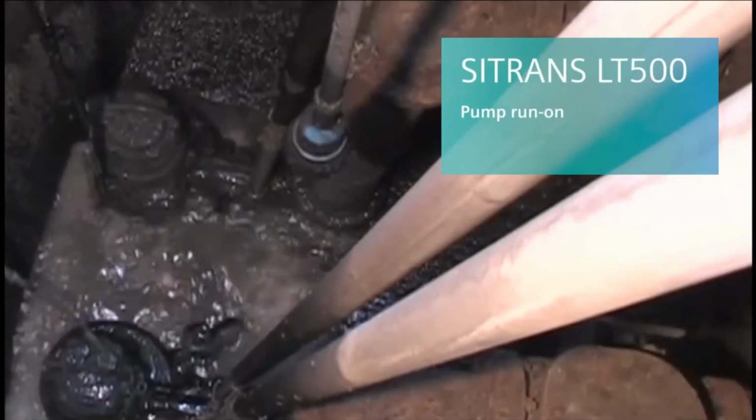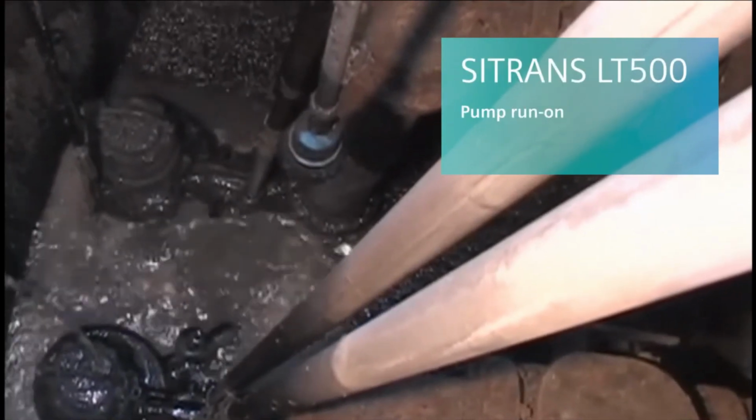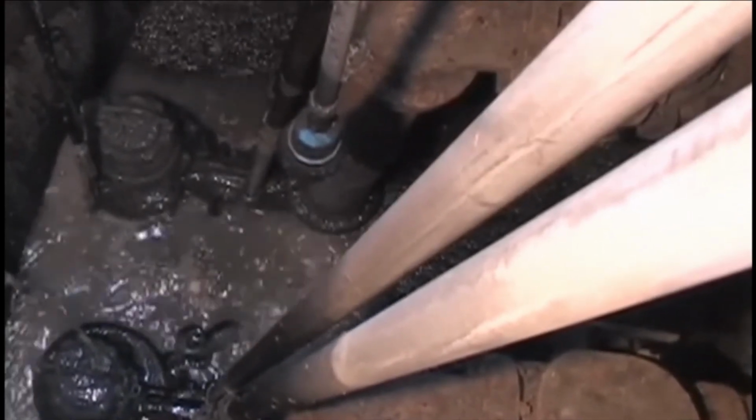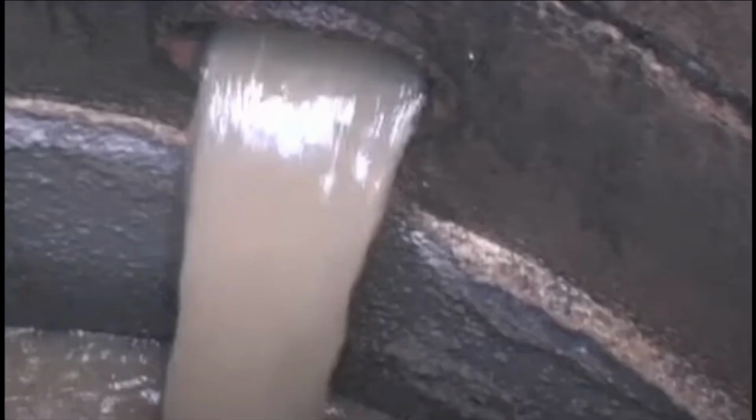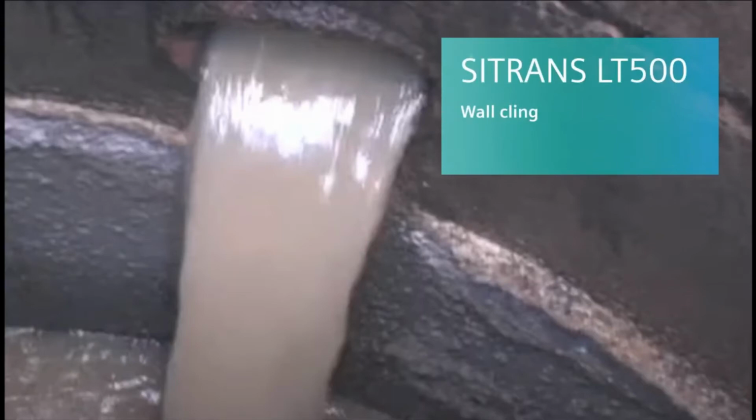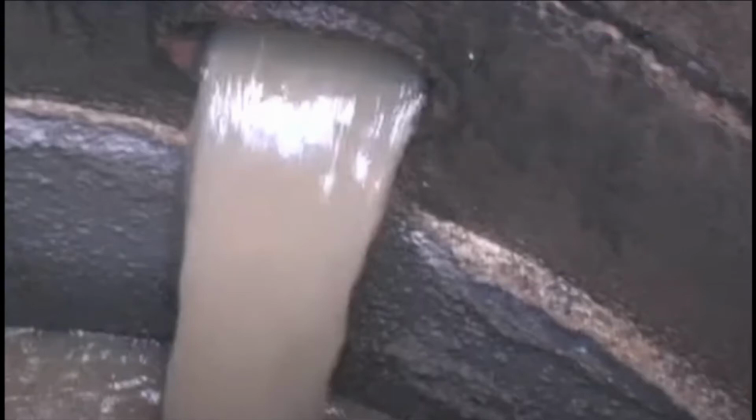We will start with pump run-on. Pump run-on is a feature in the LT500 which helps clean out the pump after the level has reached the off set point. Wall cling reduction introduces a variance into the level on and off set points. This helps ensure that buildup does not occur on the inside wall of the vessel in the same spot over and over again.